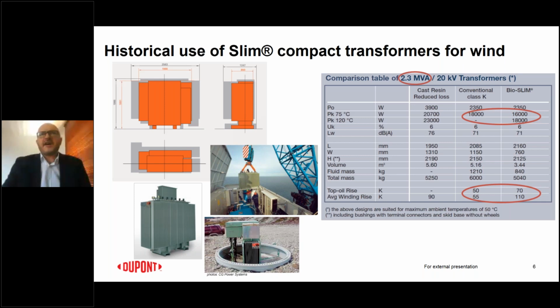When we have high temperature transformers, we should calculate losses at a higher reference temperature. It is important that these slim transformers were developed for operating at higher temperature, and even this higher temperature did not have an impact on the losses. So in terms of efficiency, in terms of meeting today's more and more stringent requirements for the efficiency of transformers, these transformers were still meeting the same requirements for the losses. So that was the slim transformer development.